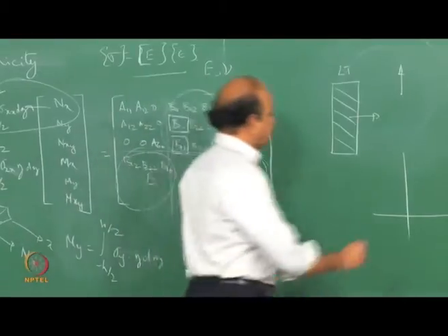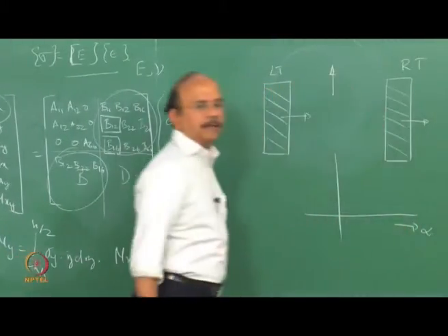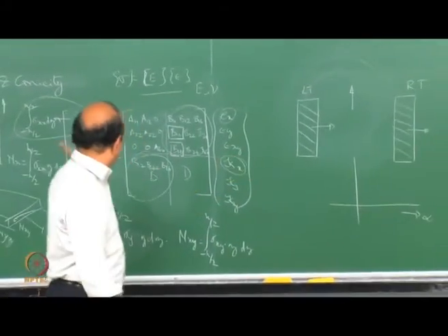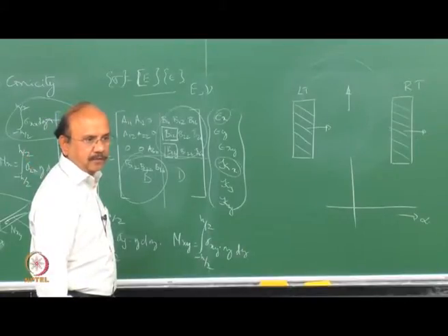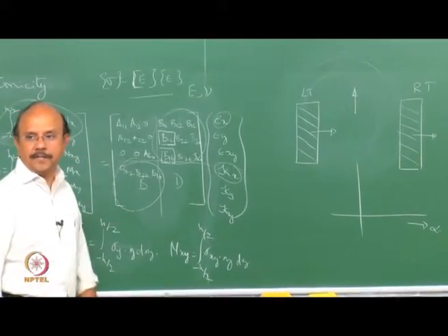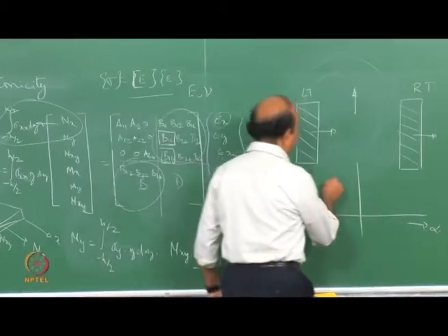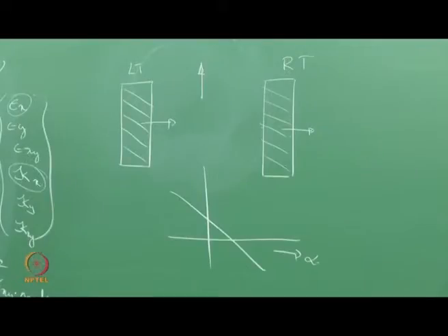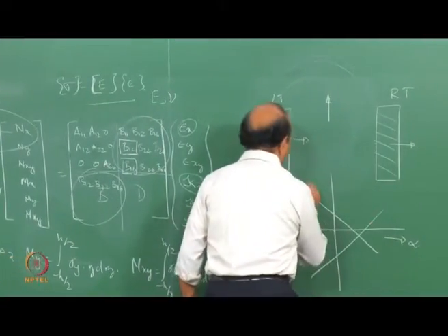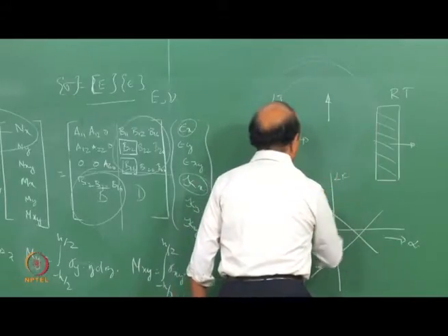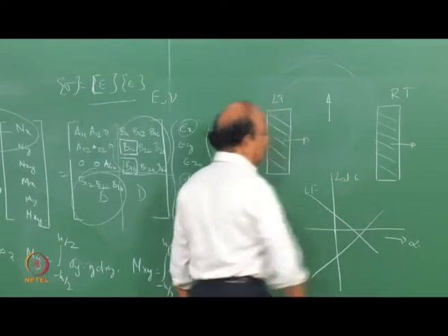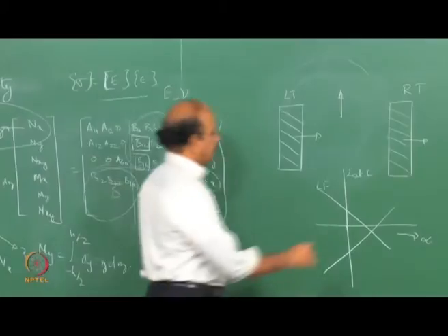I plot alpha versus both the aligning torque, a torque that happens due to the nxy term, and a lateral force, the nx term. So that happens to be like this, and it so happens that because of the directions, if this is the lateral force, if you want to call it like that, that is the aligning torque.